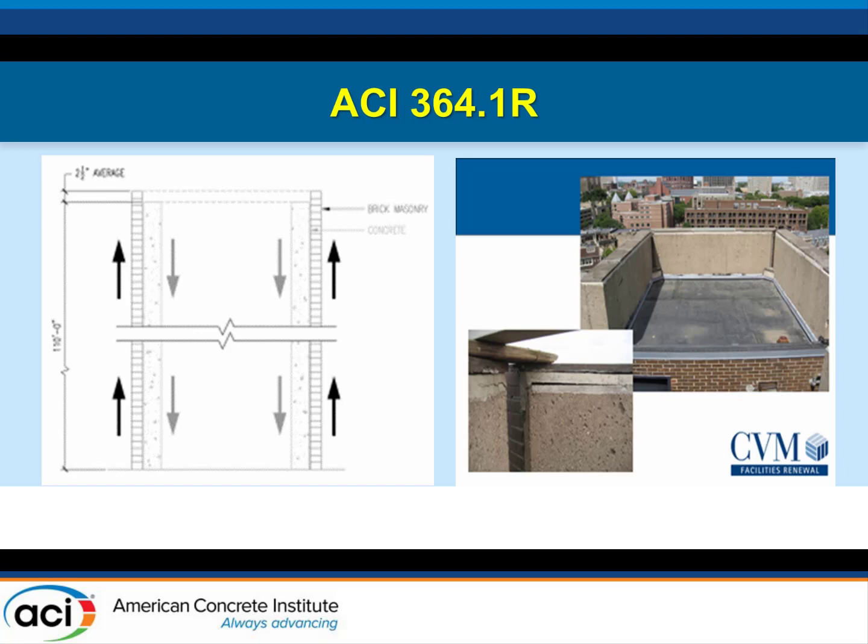And you get up to the top of the building and you look at the copings, some were still tilted, some had been picked up, and they had put grout under them in at least 2 instances. So our theoretical calculations, or just using empirical rules, are consistent with what we're seeing on the building, with the amount of movement that's happening at the top.